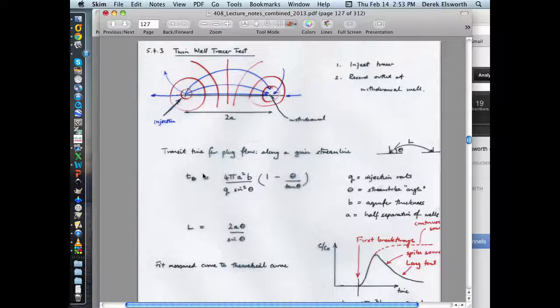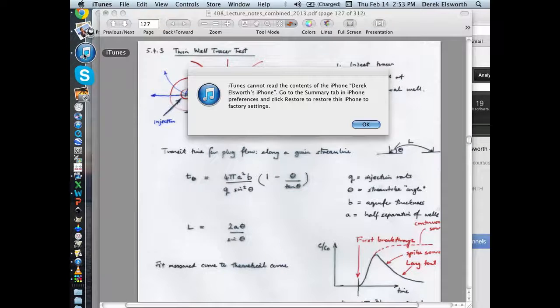Or you can upscale, and you can do a full well test, where you drill a well, you just keep on pumping out of that well, and you measure drawdown at some other location, the so-called Theis solution that you might have used. I know people have used that in the past. And the idea is that if you want a representative value of the permeability of your aquifer and how much storage it has, so you can make some decisions about your...